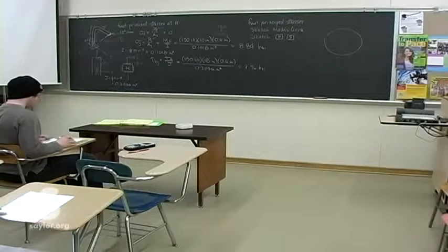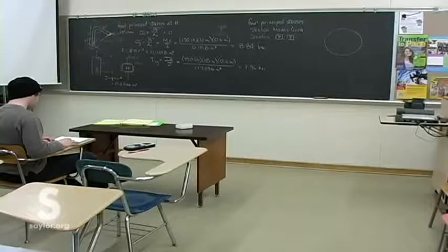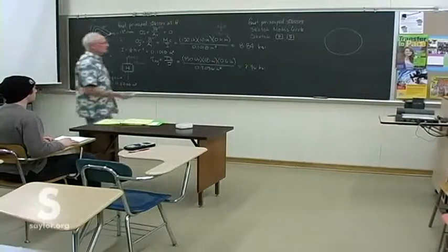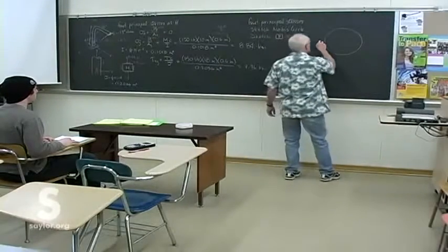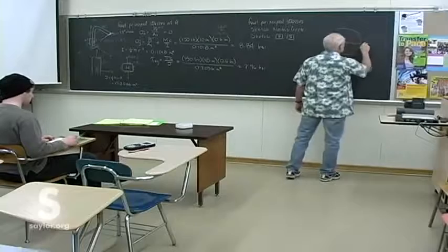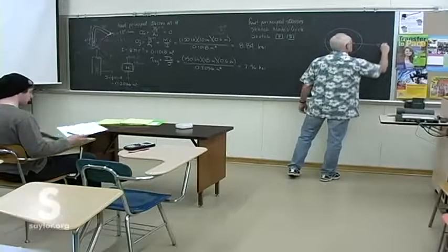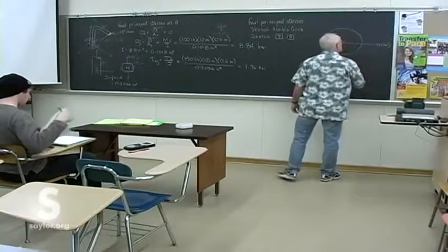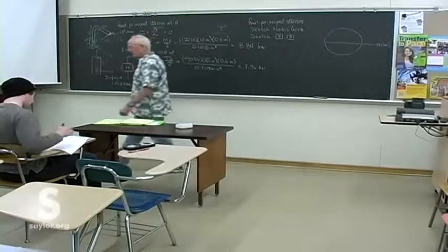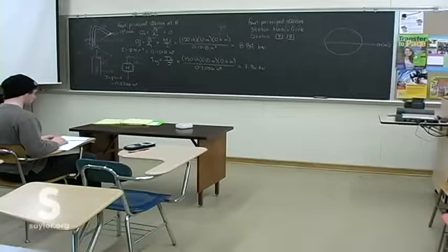Alright, so you have to figure out where the center lies, where the axes are. Of course we know where the x-axis is. It's always right through the center. The units will be KSI. Must be in both directions for everything to fit on the circle, otherwise it's going to be an oval.